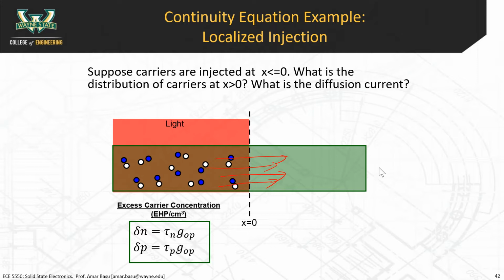It's negligible, but it's still happening, right? That's why it's a bit of a trick question. Remember our band gap: at non-zero temperatures, there's a very small probability of electrons jumping up into the conduction band. That's generation. So yes, there are generation processes, and therefore there are recombination processes also, because they're happening in equilibrium.